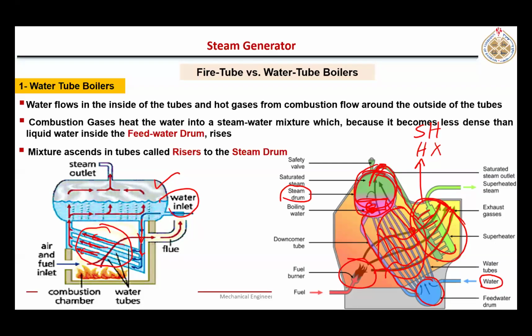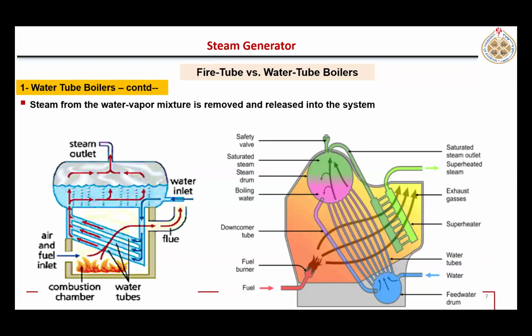density is dropping, until it reaches that vessel again. So vapor will be separated, liquid will again go down, and this process keeps on working like this. And this saturated steam is leaving from the top. Right. So there could be many different designs. These are just two simple schematics shown here. We shall see some practical designs in coming slides. These are called water tube boilers because water is flowing inside the tubes. All right.